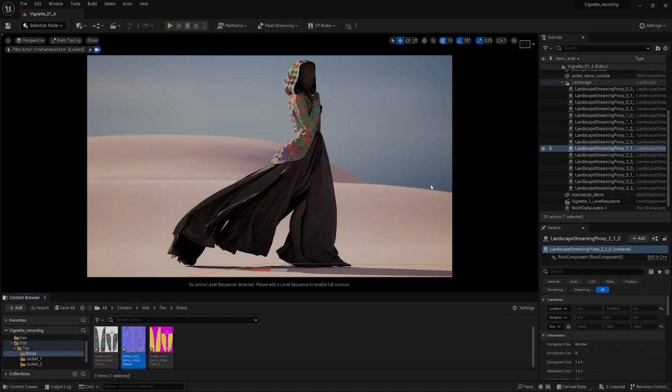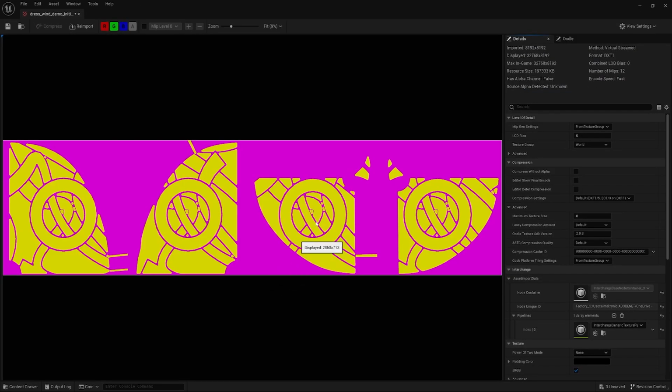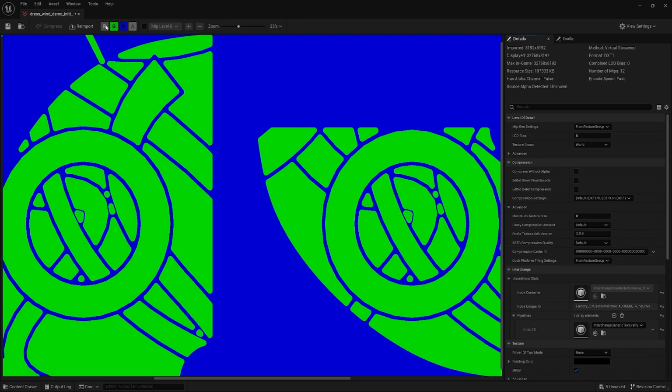Unreal Engine usually recognizes normal maps and automatically sets their compression settings. If this hasn't happened, select Normal Map in the compression settings. Set the packed texture compression setting to Masks No sRGB, as it consists of 3 grayscale maps. You can verify the maps here by turning the channels on and off.